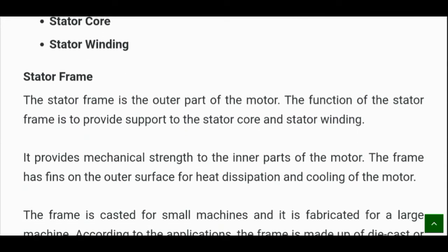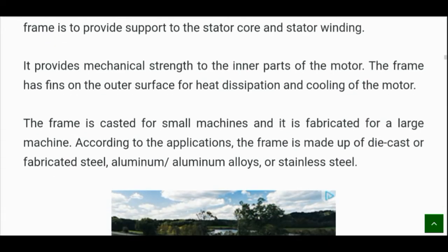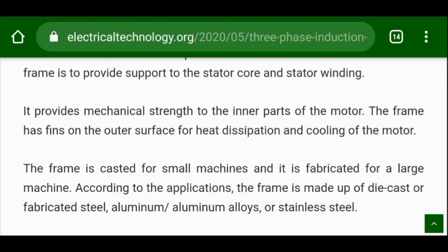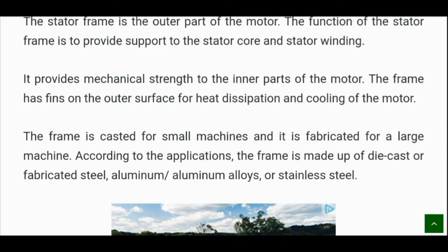What is the stator frame? The stator frame is the outer part of the motor. The function of the stator frame is to provide support to the stator core and stator winding. It provides mechanical strength to the inner parts of the motor. The frame has fins on the outer surface for heat dissipation and cooling of the motor. The frame is cast for small machines and fabricated for large machines. According to the application, the frame is made of die cast or fabricated steel, aluminium alloys, or stainless steel.